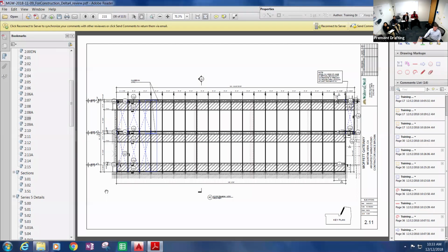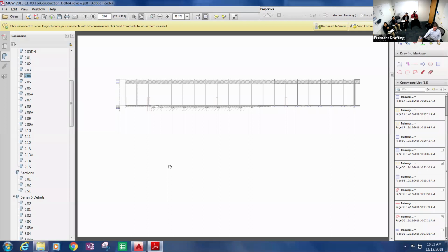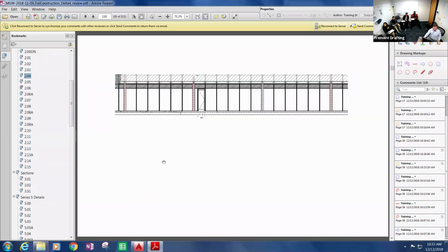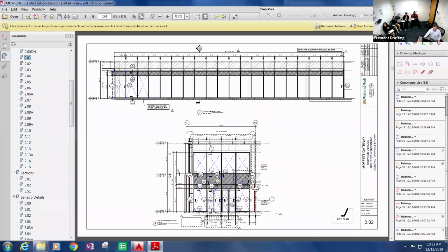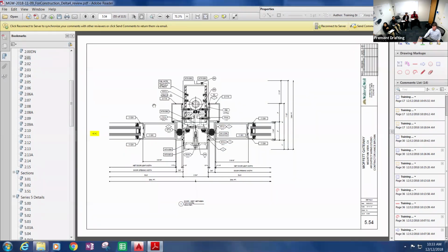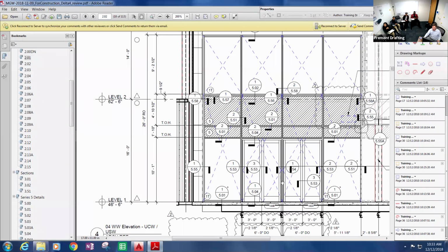I was going to say it's just a little small thing, but on the doors, our tributary area just gets a little larger. On doors, because of the flag units, and actually this one looks like it's got a full vertical, so it may not. That vertical is coming down, taking the wind load tributary area, but a lot of times our door unit might look more like this.